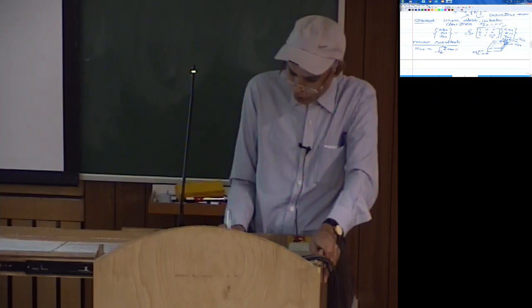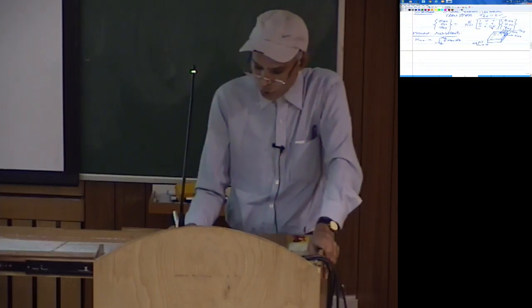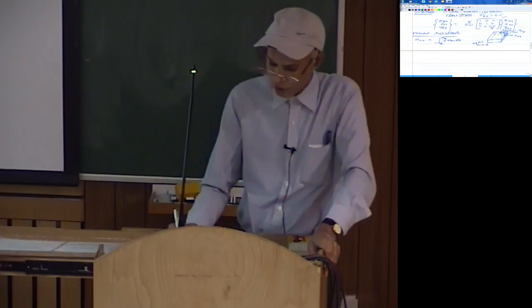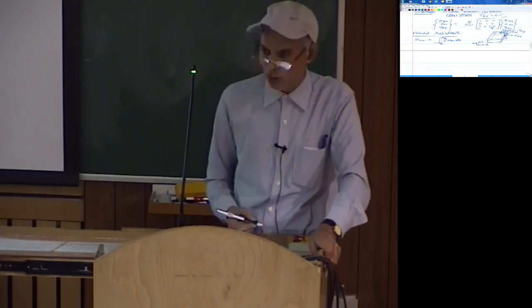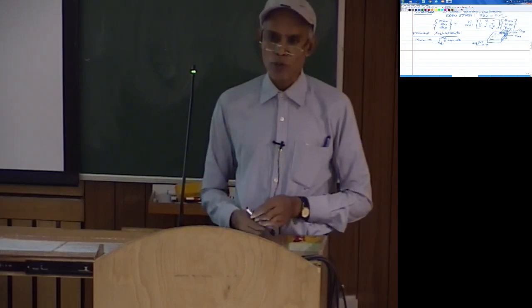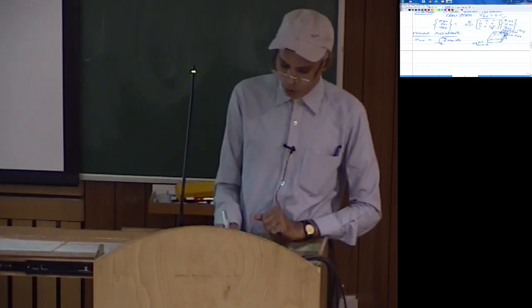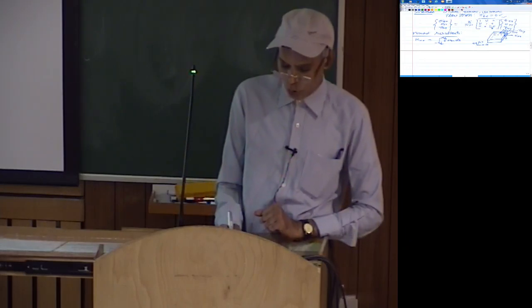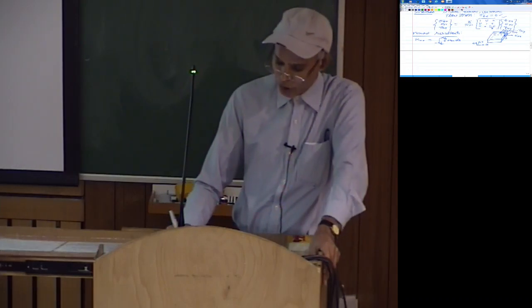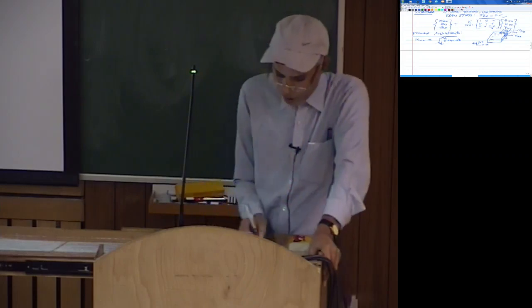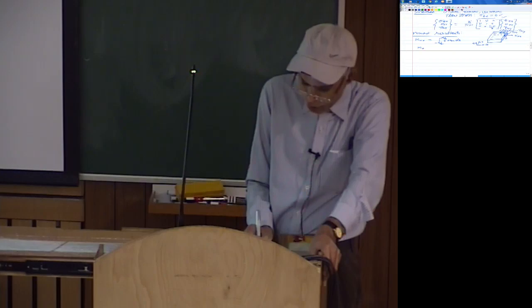So z into sigma xx dz is defined as the moment resultant, and obviously this is going to be a moment about the y axis, because the sigma xx over this area is going to produce a moment like this. That moment is about the positive y axis, and it is moment per unit y length, because we are just multiplying by z into dz, and this is force per unit area. So it is going to be Newton meter per meter, and that per meter is per meter of length along y. Similarly, if I look at this area, we define another quantity myy.